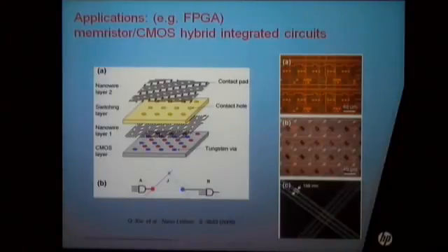If we can lift the wires and the connections from this CMOS layer and put them into another layer on top of the CMOS layer, we can put more devices in the CMOS chip, and then we can use tungsten vias to connect these two layers. So here we use a memristive layer to serve as the wires and the connections. In this case, you will have a higher device density, and the device can also be operated at a higher speed and consume less power.